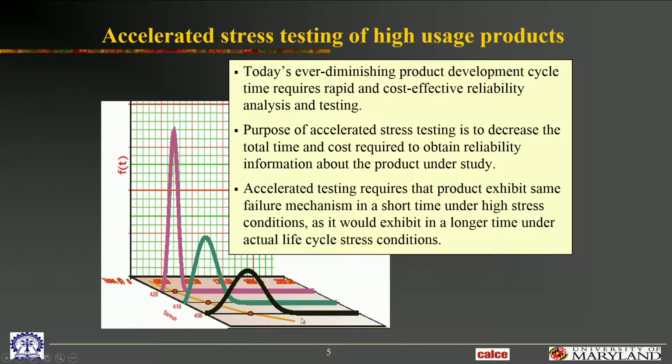And so on. You raise the temperature even more, stress even more, it fails even faster. So the yellow curve is through the means of the distribution, and it's basically trying to show the stress-life relationship. That would be like your physics. If you had a model to fit that yellow line, that would be a physics of failure model. And that's the goal in physics of failure, to come up with these stress-life models to the point where the model constants are just material properties. You don't want to enclose your design parameters in there. You just want to make the models at the material level.